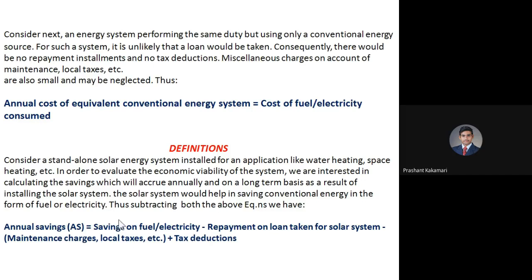So that is minus. And now, what is the benefit given by the government on interest or in discounts, or the benefit with depreciation or inflation of the system? That is all considered under tax deductions. As I told you, if companies go for renewable systems, they are not charged interest for the long term, for 10 years or 20 years. So that is also one benefit, a tax deduction benefit. One more benefit is the discount given by the government while purchasing, or the yearly electricity bill concession given for grid-connected systems. All these concessions I have considered as tax deductions.